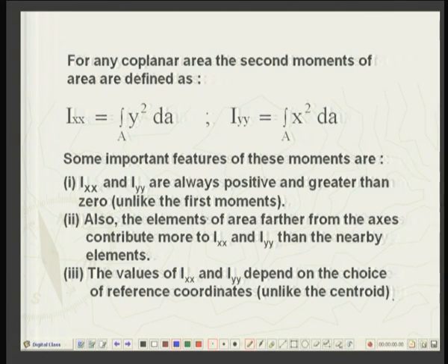Secondly, the elements of area farther from the axis about which we are taking the moments, whether it is the x axis or y axis, contribute much more than the nearby elements. As you go farther and farther, the contribution of that element of the area will be more and more, not even linearly, but quadratically more.